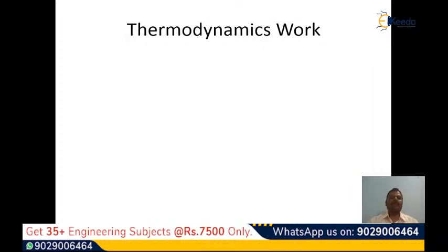Now, to define the thermodynamic definition of work: thermodynamic work is the interaction between system and surroundings. In thermodynamics, that work transfer is observed at the boundaries of the system. It is defined as follows: the sole effect on things external to the system can be reduced to the rising of a weight. Here, the weight may not actually be raised, but the net effect on things external to the system is reduced to the rising of a weight.